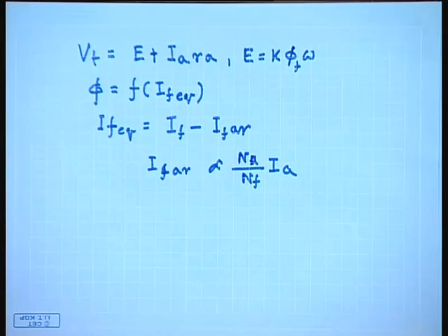armature current. Therefore, physically what happens is that as the motor is loaded, the armature current increases. As the armature current increases, armature reaction becomes more prominent, and hence the effective field flux reduces, and hence the generated voltage reduces. So, more current flows and the torque increases. Therefore, the effect on the torque speed or current speed characteristic is somewhat like this.